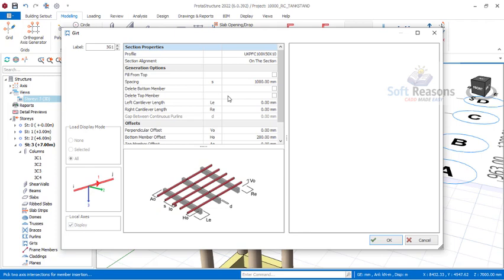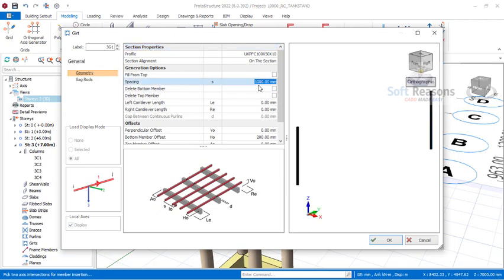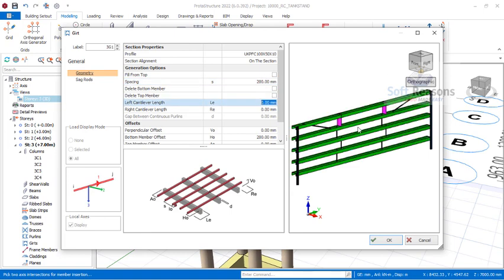Okay, the dialog is still loading. So in this dialog, you see the spacing of this is 1 meter. We want to make it 200, just 200 spacing, so we can have the horizontal poles arranged just like this. So over here we will be having it to be 100, which is the offset from the bottom.